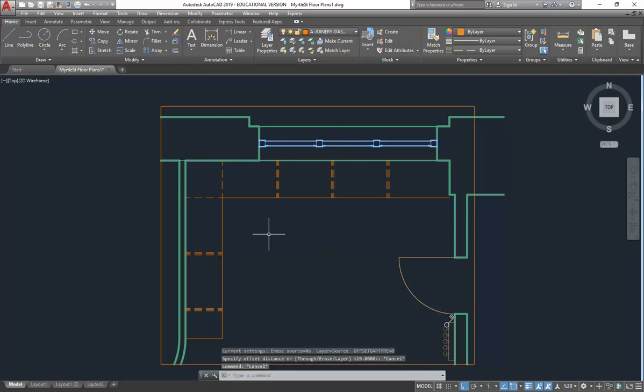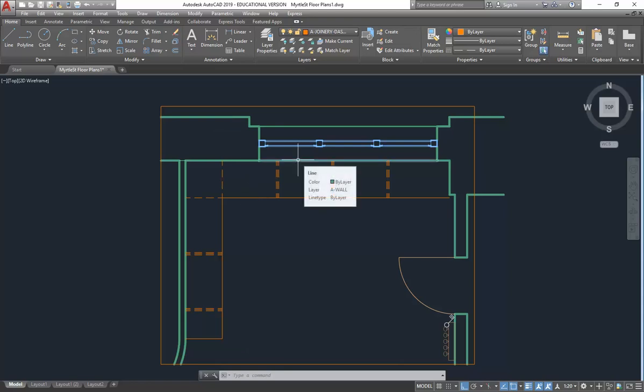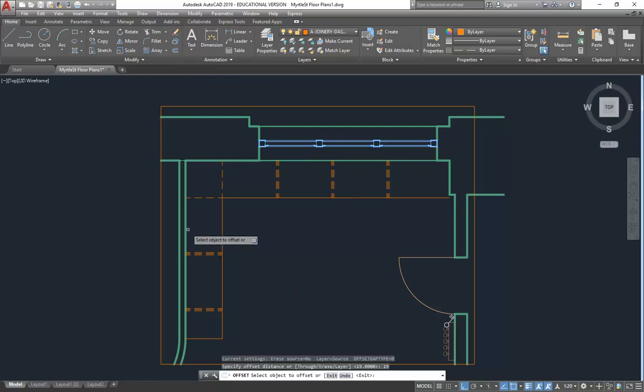Oh, now let's see actually. So it doesn't need to be waterproofed. The splashback will go on top of the cupboards, so I'll just do the cupboards right up against the wall. And actually I've done this exactly like this when I built them. I don't think there's any need to do it with a backing, but I don't think you have to. So I'm going to offset 19 from the wall.